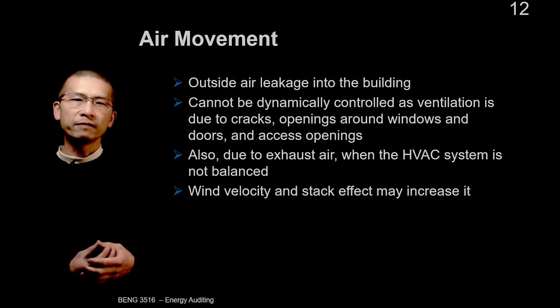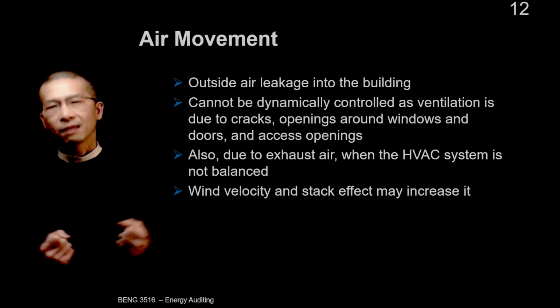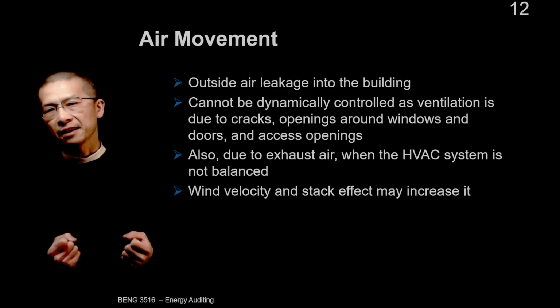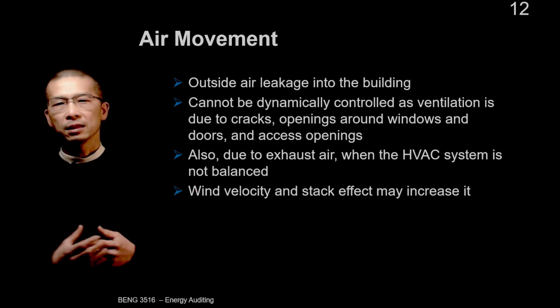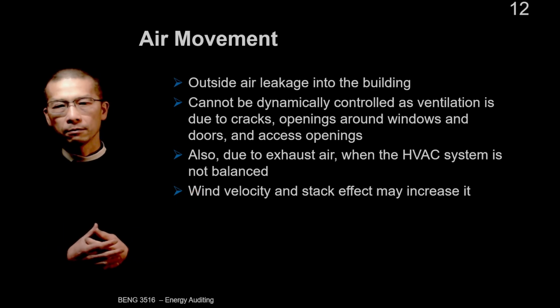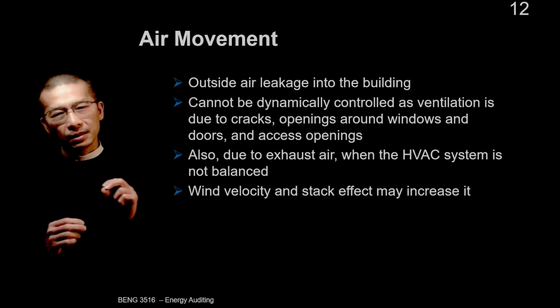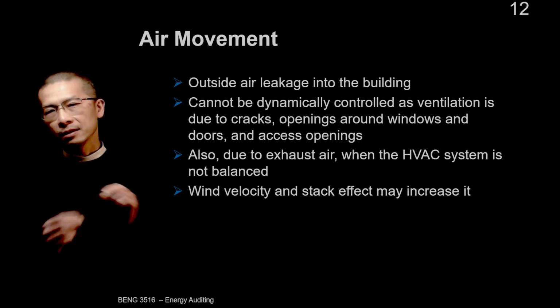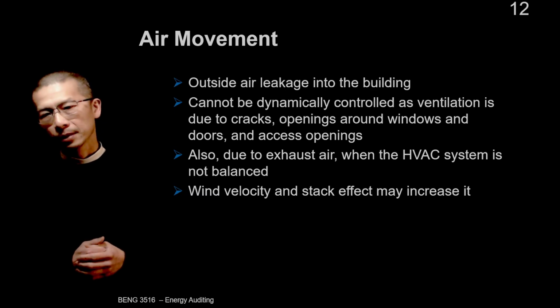This effectively turns the building into a vacuum, sucking unconditioned outside air through every tiny opening in the envelope. Air will find any tiny space in the building envelope and go through it.